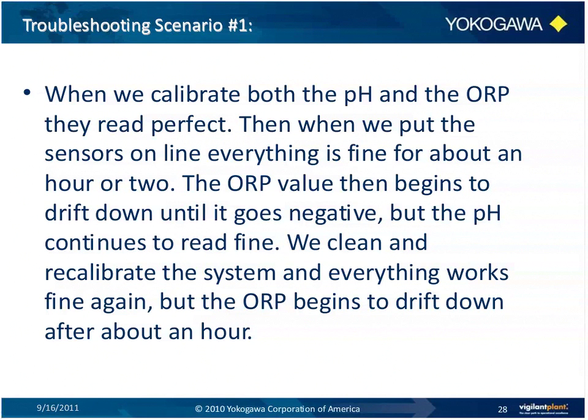If the platinum is connected to the solution ground terminal, this would be common if they're measuring using one sensor and they're measuring ORP and pH at the same time, then you could try to move the solution ground or the platinum pin into the measuring terminal, leaving the reference wired where it is. This would give you a high impedance for your ORP input, which will make it less susceptible to the polarization.